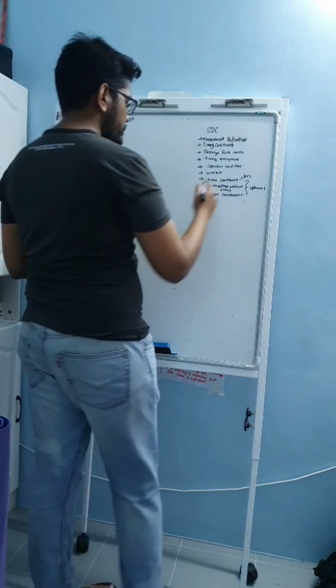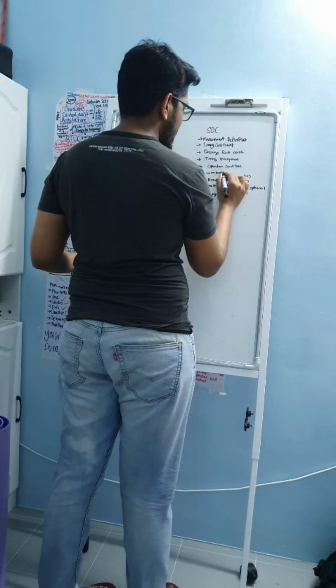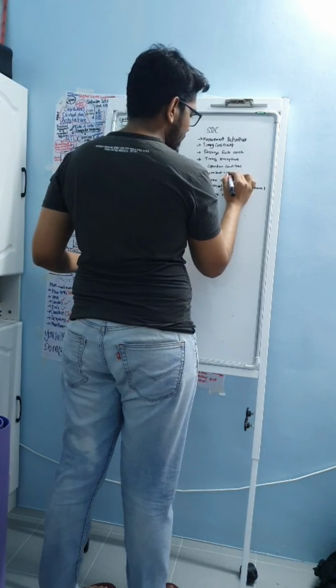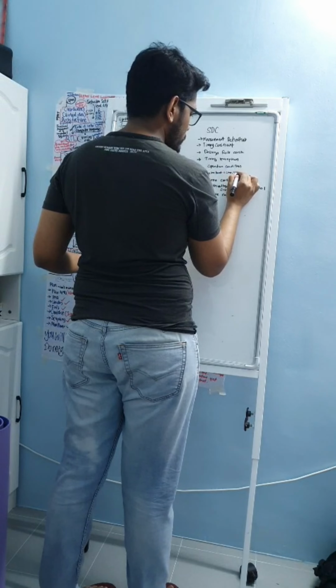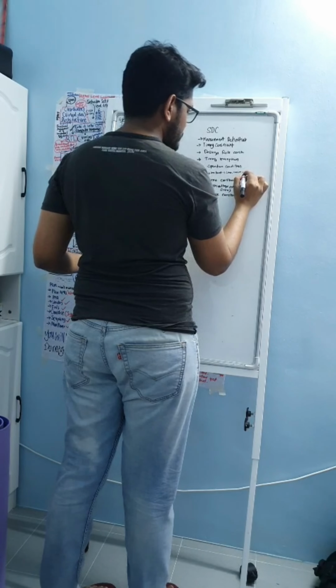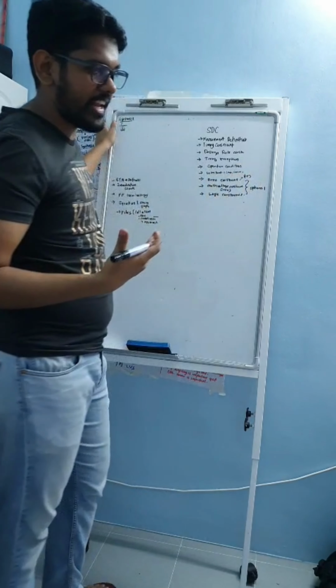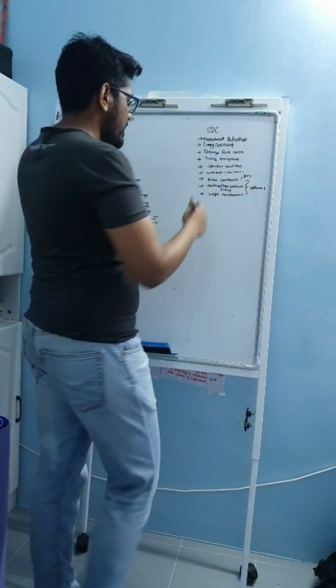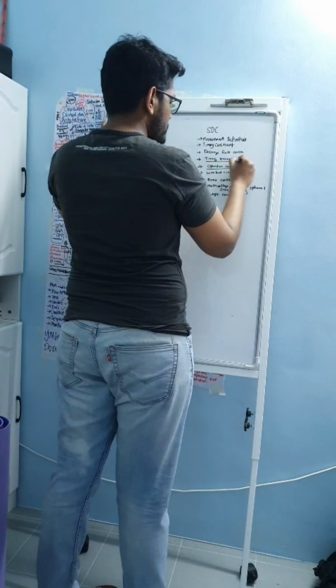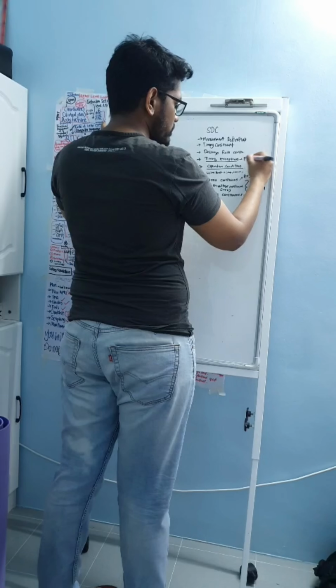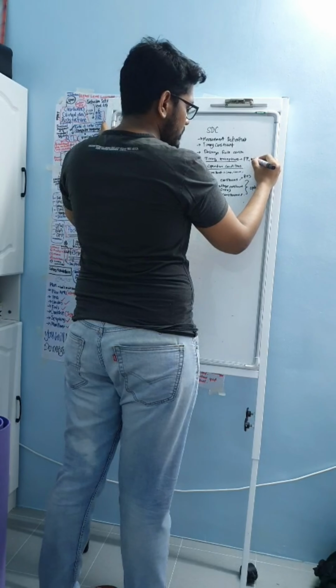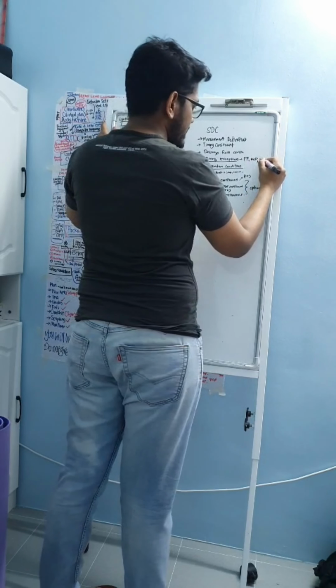As usual, wire load, you would have large and small, so this is the wire load. Maybe you can extract it by QRC as well. And then we have the operating condition and timing exceptions: false path, MCP, and set case analysis.